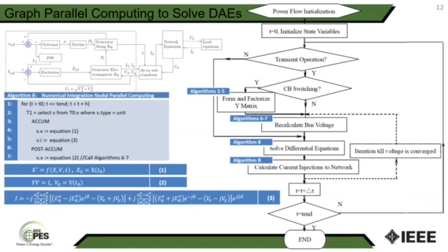Once we know the bus voltage and the reactive and active power of generators, we can initialize the state variables. If the topology changes, we need to reform and refactorize the Y matrix by using algorithms 1 to 5. Then we can calculate the bus voltage by using algorithms 6 and 7.